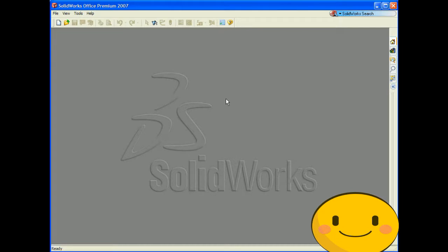This is tutorial number 1, and we will be covering how to format your SolidWorks. In this tutorial, I'm going to show you how to choose the unit standards that you'll be using in your SolidWorks, and also how to choose which add-ins you have running in your SolidWorks at one time. To start off, let's open up a brand new part file.